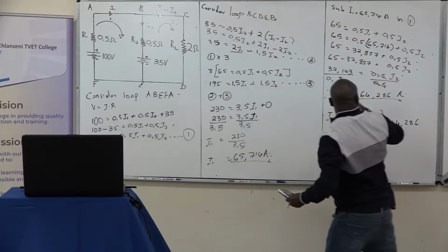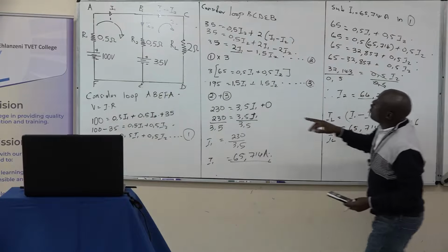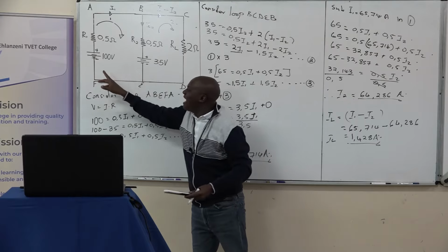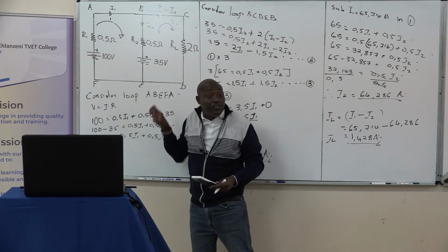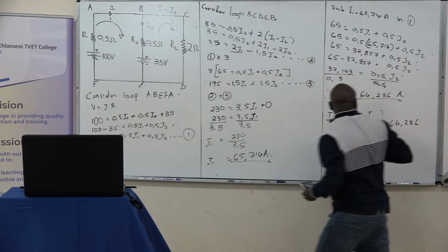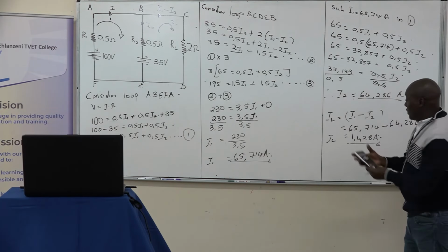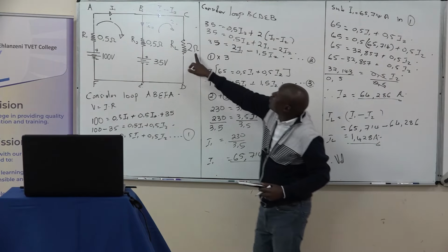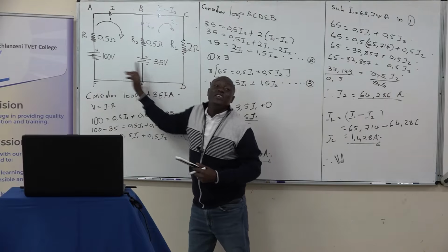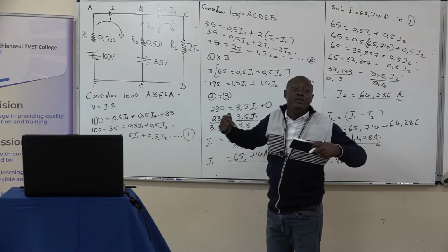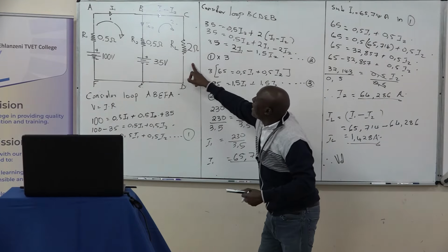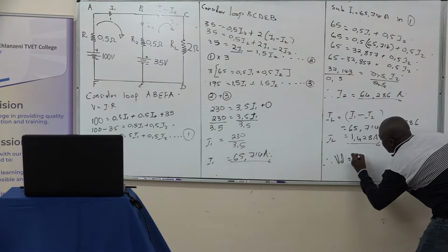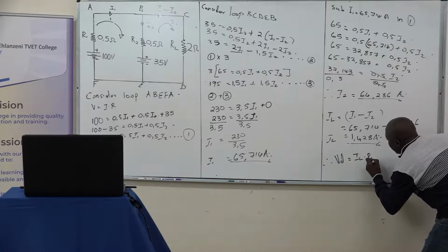Even if you check the value of the voltage drop, if you calculate it, it is going to be lesser than these two voltages due to the current I have. We can prove that by comparing the voltage drop across the load with these two. The VD is equal to the I load multiplied by the R load.